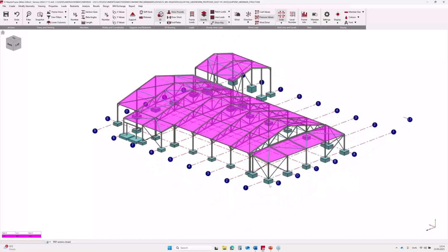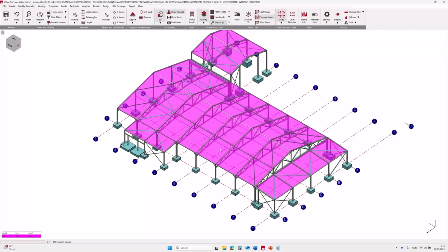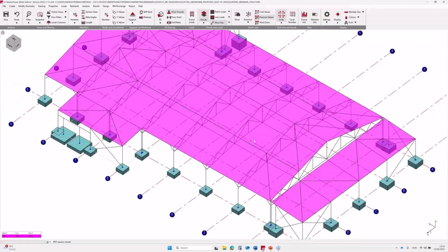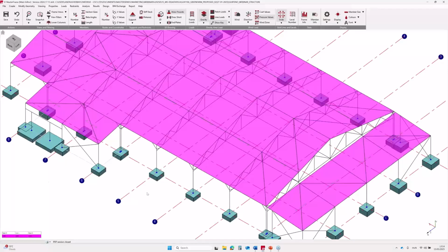So we have full area loads. Area dead and live loads were applied to the model using floor and roof area loading panels. The area loading panel is an extremely useful tool in applying gravity, dead and live loads across the floor and roof areas of a model. It enables you to apply loading to floor panels and have the loads automatically distributed onto the members around the perimeter of the panel, depending on which directions you have chosen to span the panel.